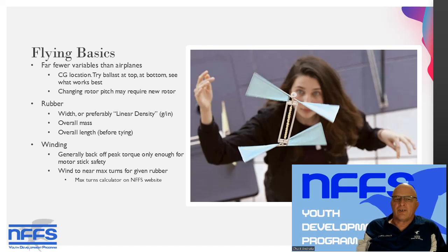You can try changing the center of gravity. So if you have a little bit of ballast on it to bring it up to weight, try it at the top and the bottom. See what works best. You might be surprised. Intuitively, it might make sense to have it at the bottom because that's hanging down. But try it at the top. See if it flies better that way. We've seen different experiences with that.